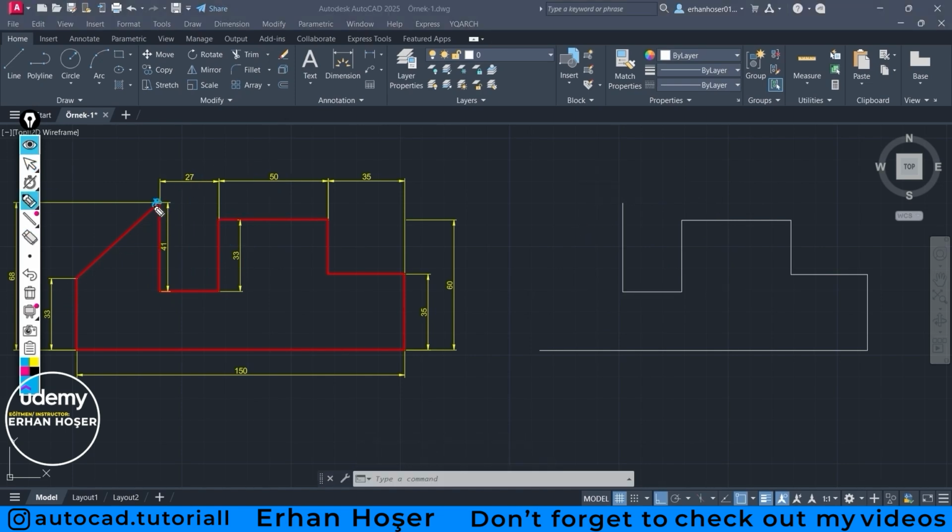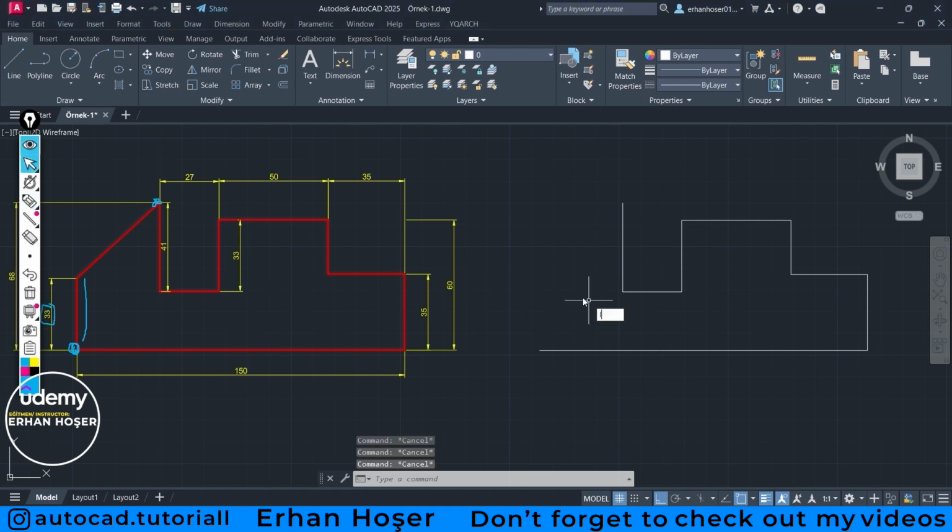There's a diagonal drawing from here to here, but there is no angle or measurement here. So let's not draw this, but let's draw this lower part first. Look, right on the left side it says 33 units. I pressed L, I pressed space. The starting point, that is, I clicked here and pulled my mouse up, 33, enter.